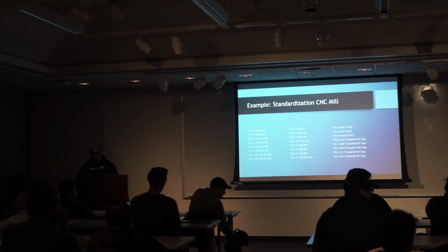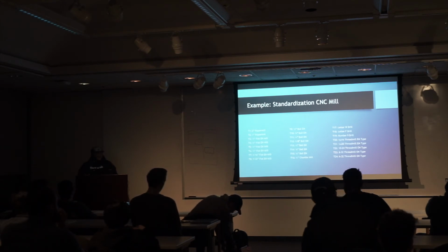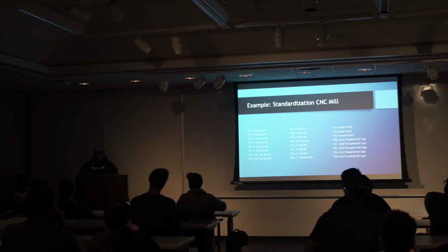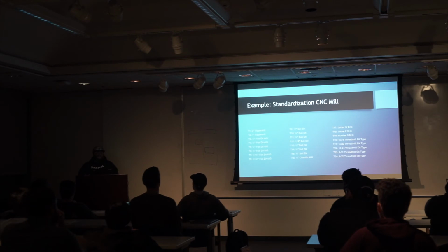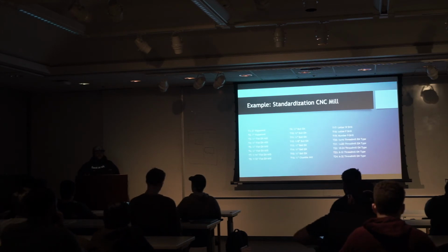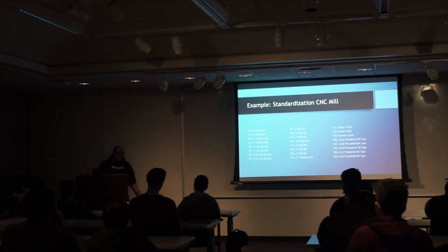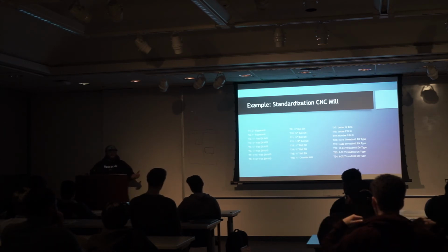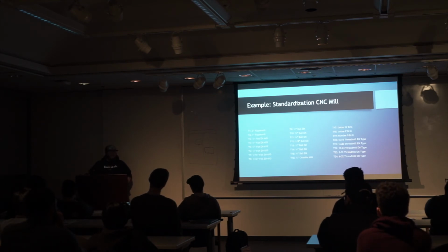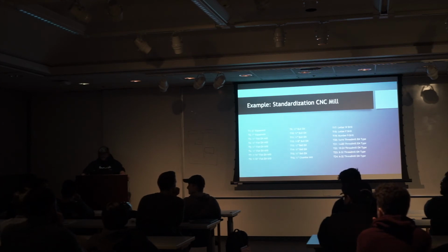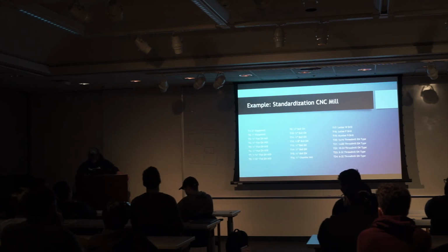Is this a good example of something that you recommend pitching to Matt? Yeah. At the end of the day, it is his machine, right? That's the other issue. There are ways to do it without affecting him. We all know he really doesn't use the machine that much. But when he does, you could just have the numbers in an Excel sheet for all your tool offsets or work offsets, because those aren't going to change if you set this up correctly. Then you could take everything out of the machine if you need to use it, clear it, and when he's done, just type all the numbers back in. It's not ideal, and it does add a step in which someone could fat finger a number and drive a drill into the table, but it's better than nothing. I did already pitch it to him, and he loved it. Kyle's a good person to answer that question.